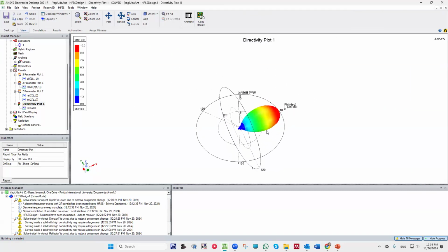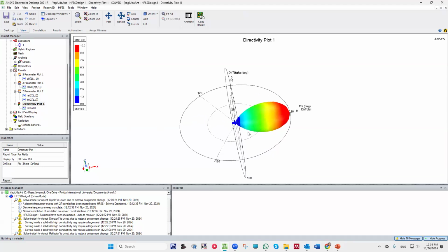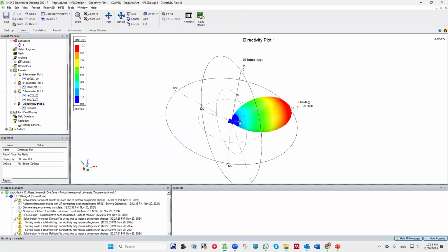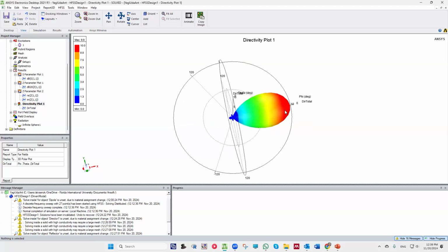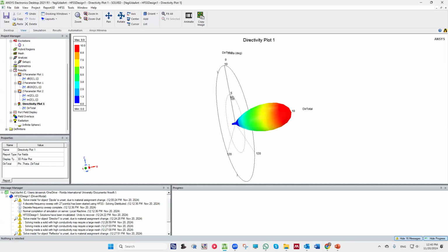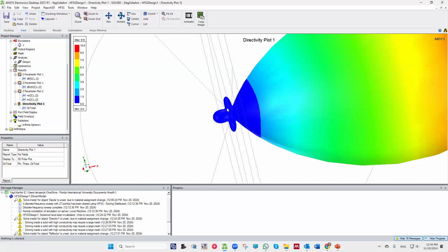And the directivity pattern at the frequency 2.2, which is close to the optimum, is this one. So you see that now it is a very directive radiation pattern. Thus, the vast majority of the radiated energy is radiated to the forward direction, and the backward radiation is very significantly suppressed because of the presence of the reflector element.